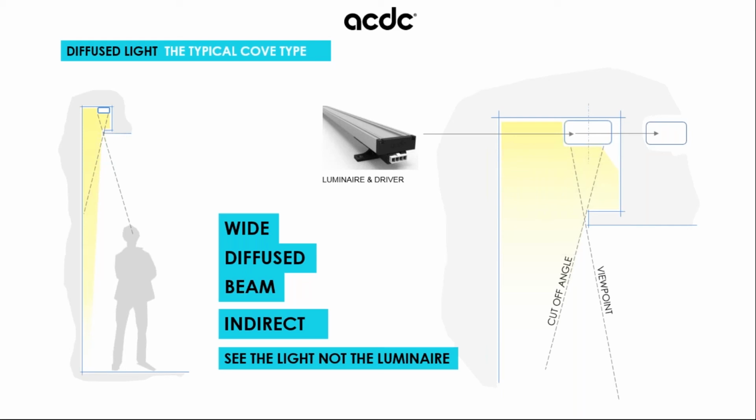What I would also recommend is that we start to think about finishes now as well, okay? So we need to think about that in the best way of really getting the best lit effect across is to look at having a matte finish to the internal surfaces of your cove. Okay, if you've got a reflective finish, and I'll come on to a couple of images in a little while, you're going to start to see an image of the light source, maybe of the LEDs, which is something you really don't want. And what we're now finding is that that cove space is being squeezed all the time.